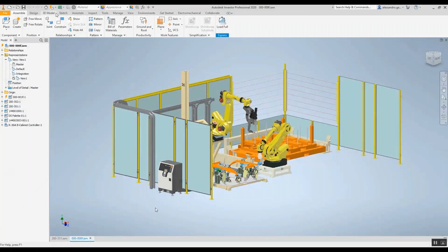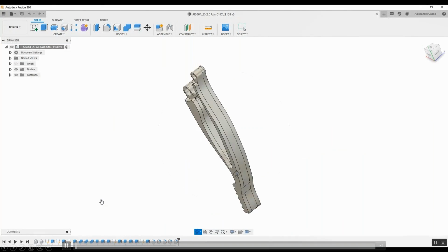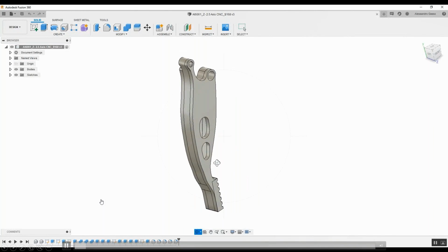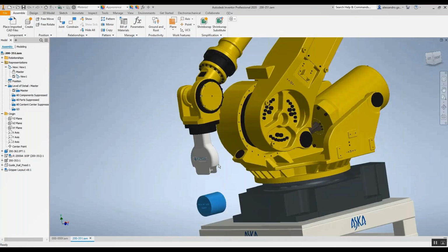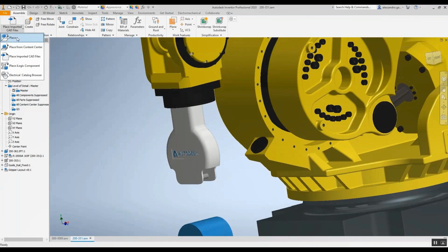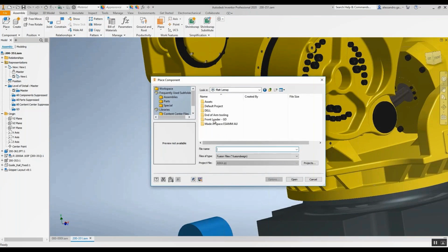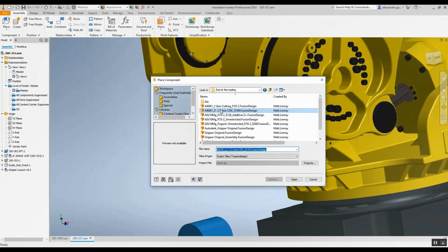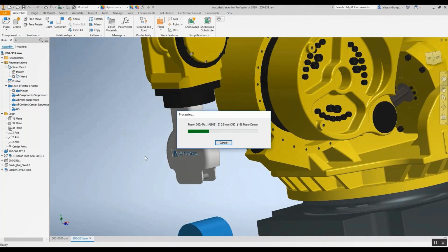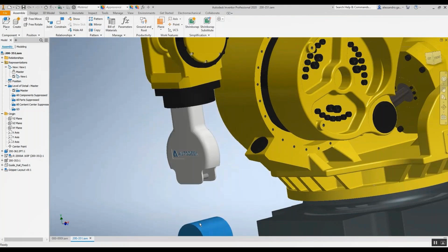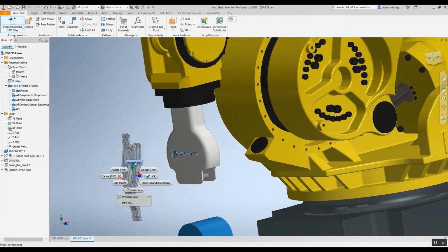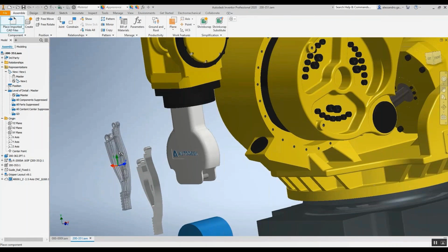So once we have our generative component, and this is showing actually the subtractive, the 2.5-axis subtractive component that we created, we can go back into our Inventor assembly and bring that right back. So again, the idea here with generative design and Fusion is not to replace what you do with Inventor, it's to give you an added step to do something that you couldn't do before. So here within that Fusion team file, you could see all those different selections for those generative outcomes, and we can bring that right back into Inventor, remake those generative components within our assembly, and then very quickly, we've explored and created a higher performing outcome.